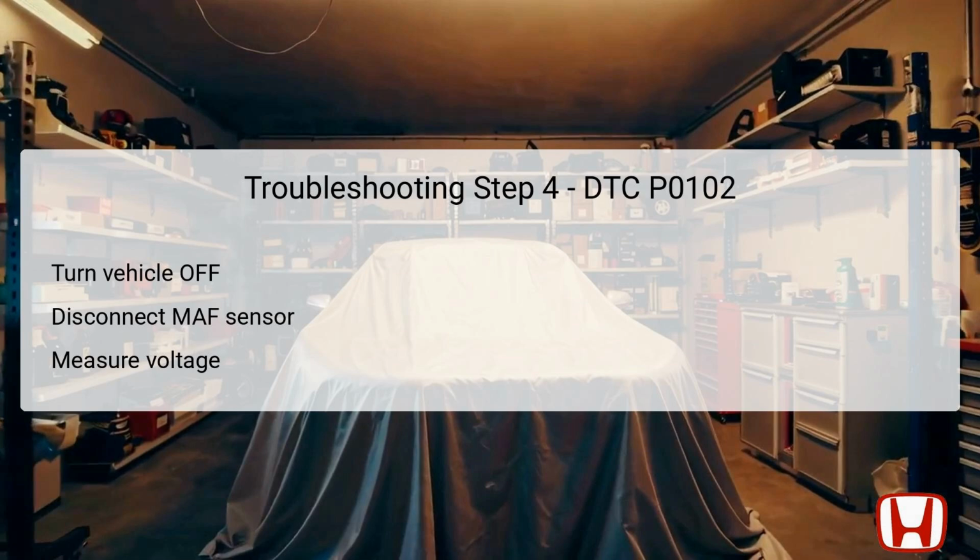If no voltage is found, troubleshooting must focus on repairing any breaks or faults in the IG1 ACG circuit. The fifth troubleshooting step involves switching the vehicle to the off or lock mode once again. Here, the technician must measure the resistance between specific test points at the MAF IAT sensor 5P connector. This check is important to ensure that the VGP line is functioning as expected, and ideally, the resistance should fall within the range of 190 to 210 kiloohms.